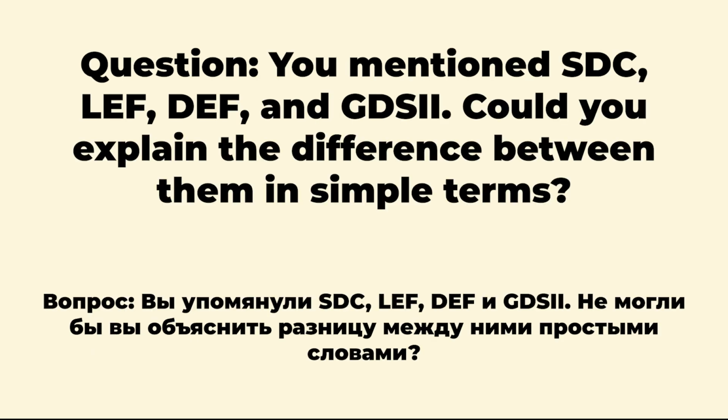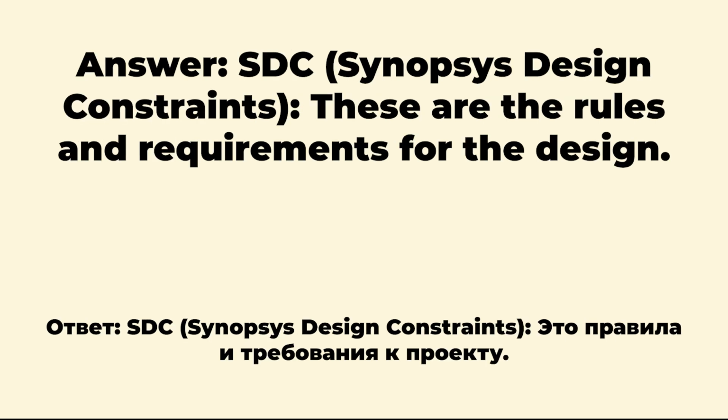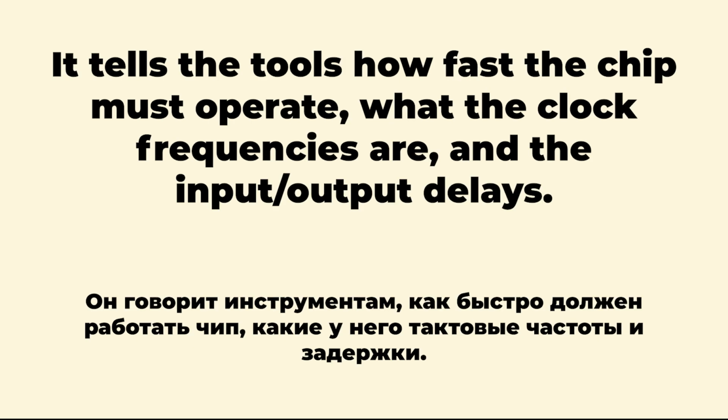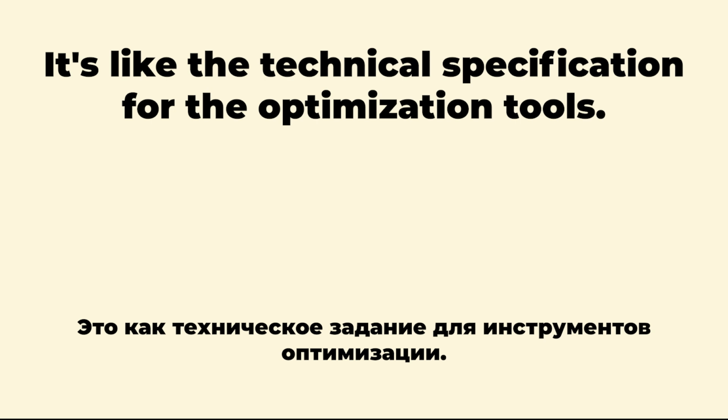Question: you mentioned SDC, LEF, DEF, and GDSII. Could you explain the difference between them in simple terms? SDC, Synopsys design constraints. These are the rules and requirements for the design. It tells the tools how fast the chip must operate, what the clock frequencies are, and the input-output delays. It's like the technical specification for the optimization tools.